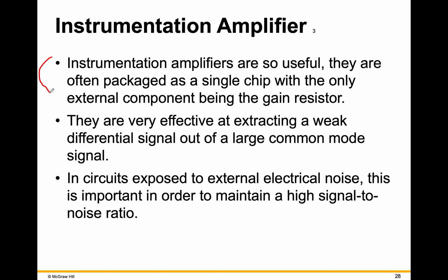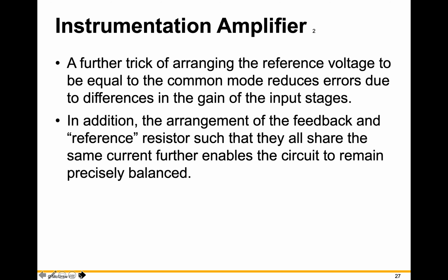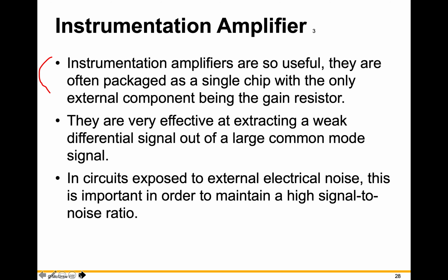Instrumentation amplifiers are so useful that they're often packaged just as a single chip. So instead of building this circuit out of all of these op amps and having to put this on a breadboard, you actually buy the entire circuit, and the only thing that you're changing is the resistor. One application of this, in my lab, we measure biomedical signals. It's a really effective way of extracting a weak signal out of a large common mode signal.